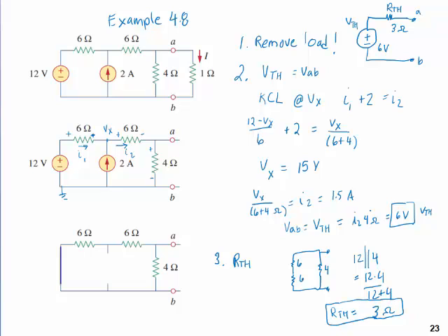And so I can put my load resistor on here and determine what the current is by doing an analysis with this whole big circuit here, or I can put my 1 ohm load resistor back on here, and analyze this circuit and determine what the current is in there. So step 4 was determine the load current, I load.